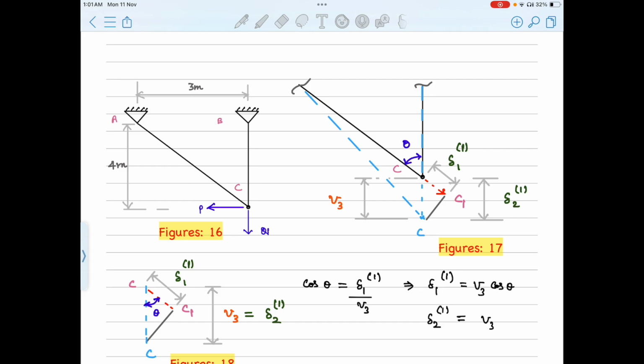Okay, this is already vertical, right? So when we draw a perpendicular line, this goes like this, and the earlier tangent line was like this, right? So the intersection of this gives this new position C, that is the deformed position, right? So from this process, we get the point of intersection as C in blue. That is, if this geometric arrangement is met, then the compatibility between local and global degrees of freedom is established.